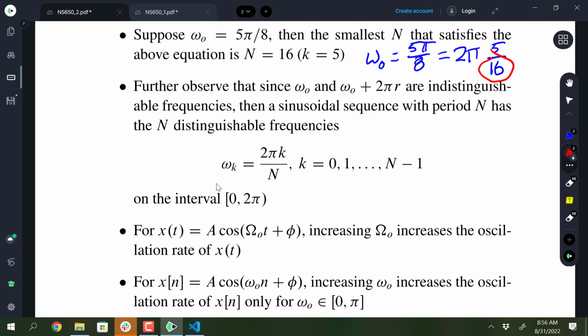So there's that relationship, and then there's also the relationship in sampling theory that you have aliases. If you're sampling at 1 kilohertz and you go above the folding frequency, say you're at 4 kilohertz and you go above up to 6 kilohertz, 4 kilohertz and 6 kilohertz end up being indistinguishable. So it's a similar idea. It's not quite identical, that's a little bit of an added twist on top of that.